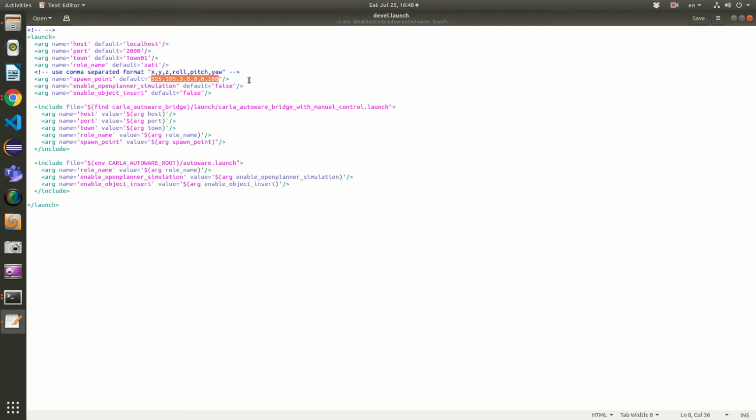Here, if we want to use random selection, to ask CARLA to select randomly, we need to keep this empty. Here I gave a point. One would ask, where can I get these values? Each map is different, and I don't want to select a random point myself and then have the car inserted in an obstacle or a sea or somewhere. I want it on the road, on a specific road. I will show you later how to find this from the OpenPlanner logs itself.